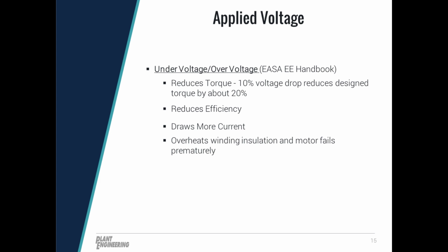The 460 volt rating there is taking into account a voltage drop in the distribution line coming from the nearest substation or distribution transformer. We have completed testing at our lab here in Raleigh that shows a slight increase in supply voltage above rated voltage will lead to an increased motor efficiency. But at the same time, that testing showed that lower voltages are detrimental to motor efficiency.